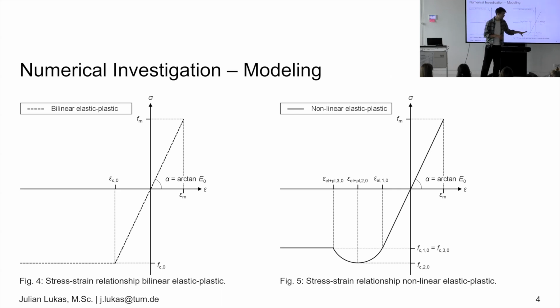values I know from Erhard, for example, and then I used the current guidelines, or the first guidelines for timber structures, which are based on a new standardization, also from steel, where we now have some rules on how to deal with finite element design in steel or timber engineering. And then I have a growth to 85%, in that case of beech glulam, where I reach my proportionality limit. Then the plastification occurs until I reach the compression strength.